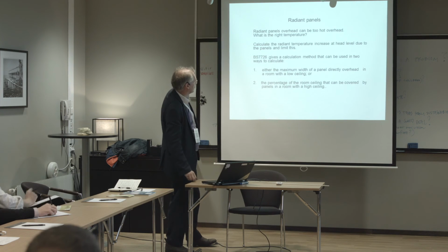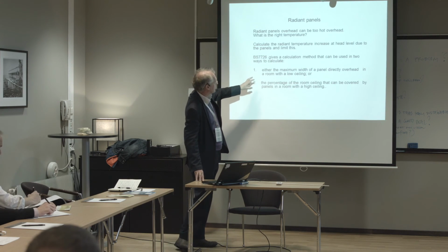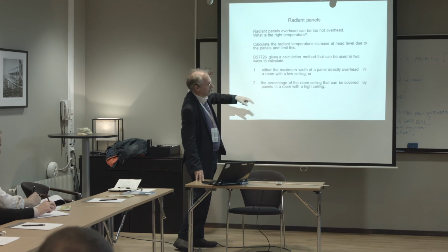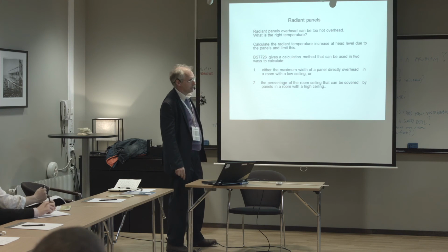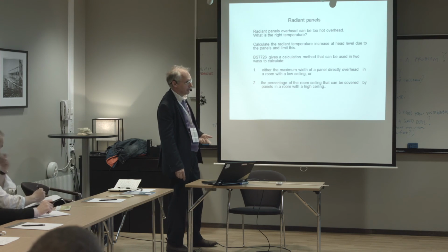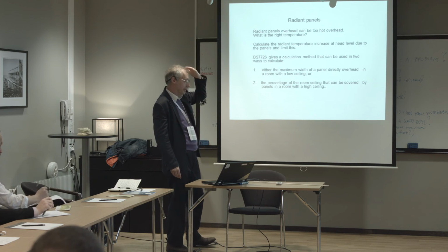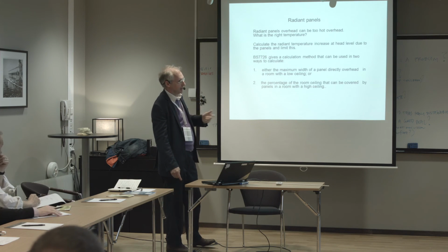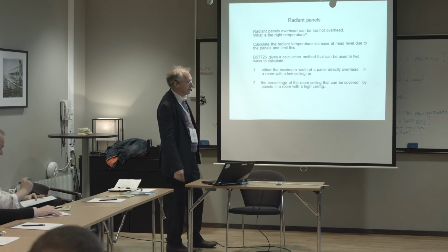And then I do have this problem with the comfort temperatures, so I think we need to go to BS 7726 and talk about the difference in plane radiant temperature instead of asymmetric temperature difference, which is what the ISO standard asks you for. And that might have wider application in that I believe the comfort temperature at head level is important, not at 600 off the floor. So I think maybe there is something that needs looking at in the comfort standards.